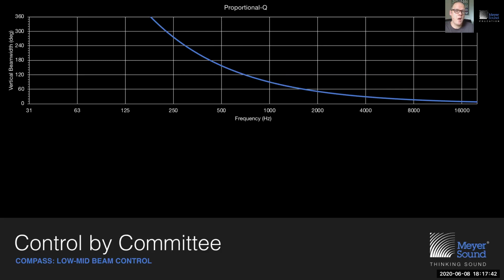This is the building block that we now need to use in such a way that we can string them together, constructing a line array, a curvilinear array while making a line array out of it, and somehow arrange those elements within a line array to achieve control by committee, to achieve a desired coverage pattern by committee, using a loudspeaker that is omnidirectional in the low end and very directional at high frequencies. And that means that we need to leverage two mechanisms against each other to pull that off.